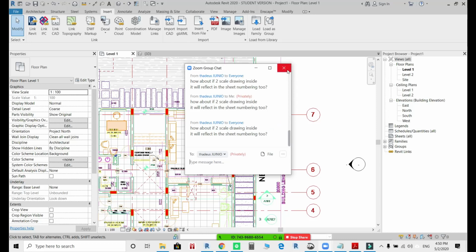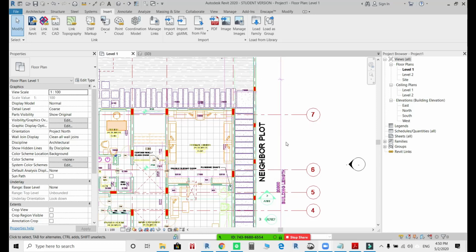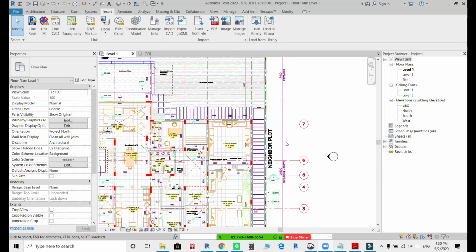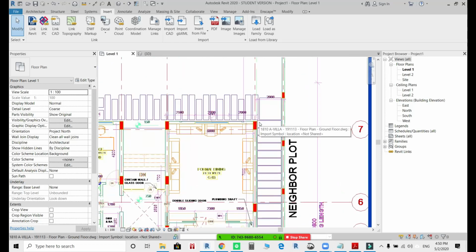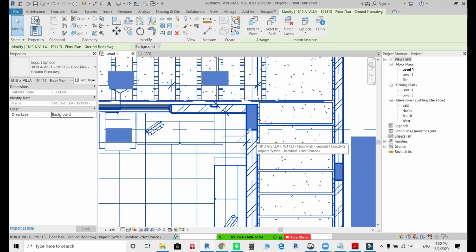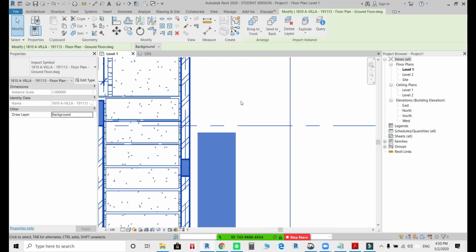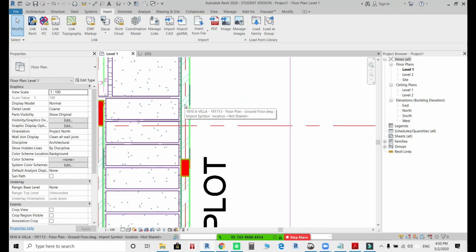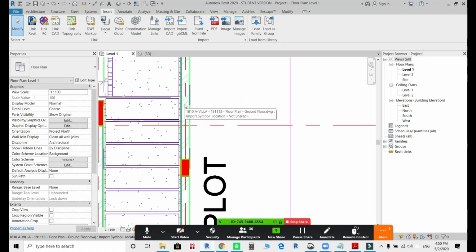Okay. Mustafa, can you hear me? Yes, I can. I have a question to you. You exported the file from AutoCAD to Revit, and now when you came close to any line, it became something like a block. So we're not able to do any changes on the file? Yes, unfortunately, because this is a 2D file from AutoCAD, so it's just 2D lines. It has no BIM properties.